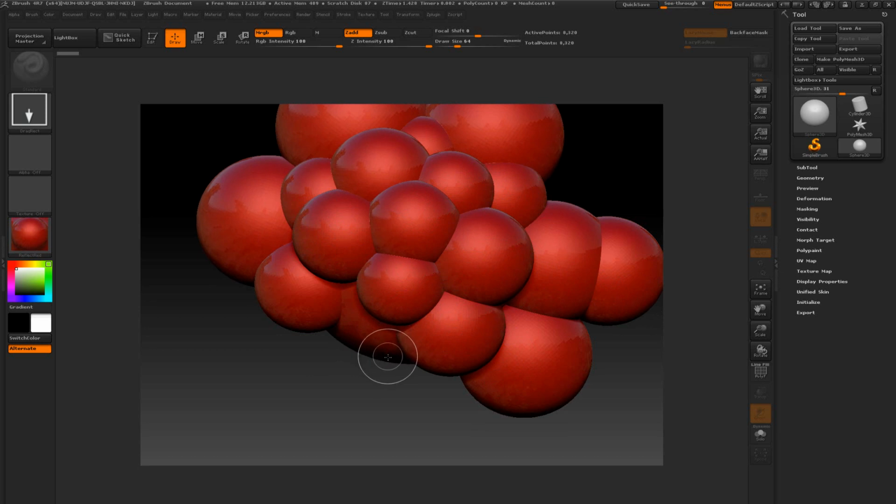The reason for this is, again, because ZBrush is a 2.5D program. So the way it works is once you make an object or 3D object that you would like to work on, you're actually going to have to make it a polymesh 3D object. So let me explain what this means. I'm going to press Control N to clear my canvas.